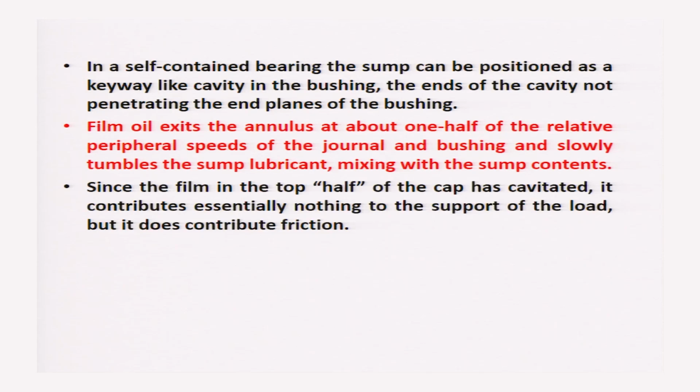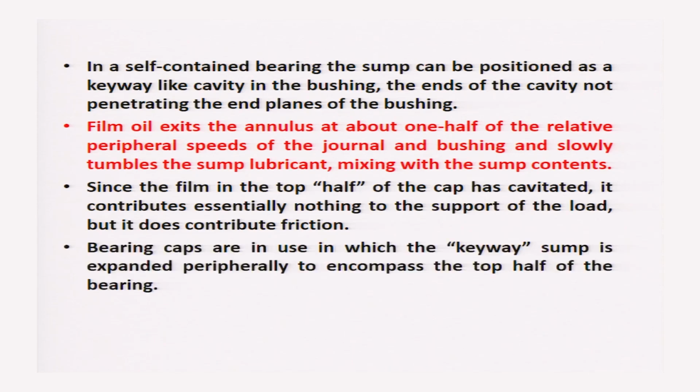Since the film in the top half of the cap has cavitated, it contributes essentially nothing to the support of the load, but it does contribute friction.